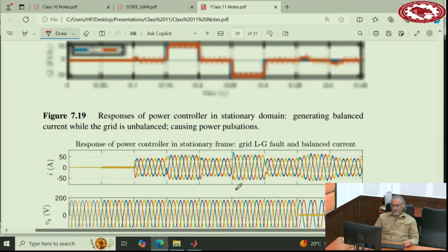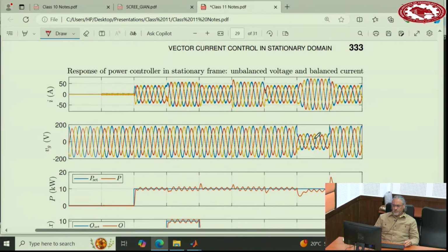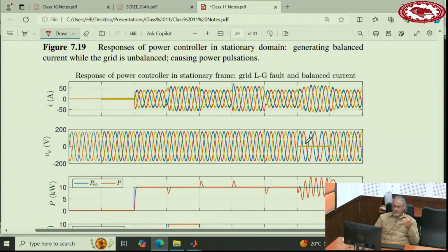This scenario is because when I said voltage drops, all three phases drop equally. In a three-phase system, this may not be the case. They have different situations. For instance, maybe one phase drops to 0, two other phases do not change. This is a single phase to ground fault that happens. So I check that situation separately.